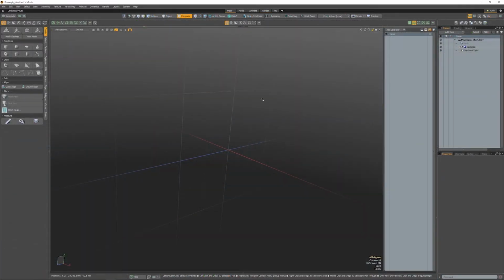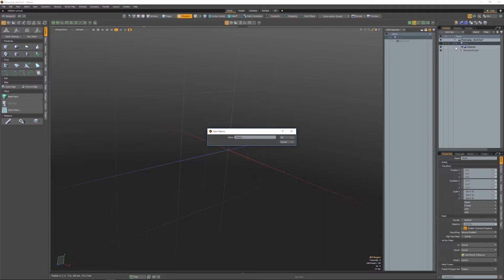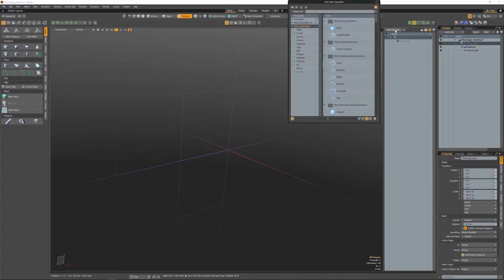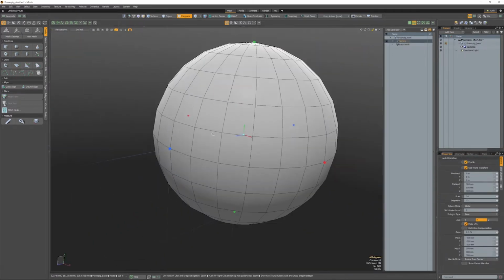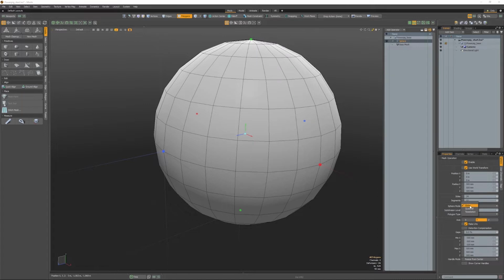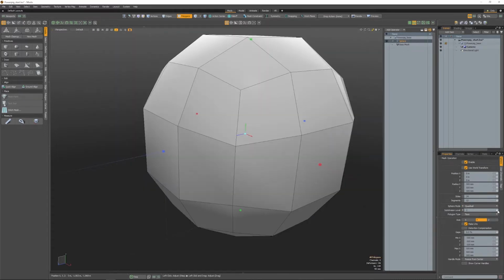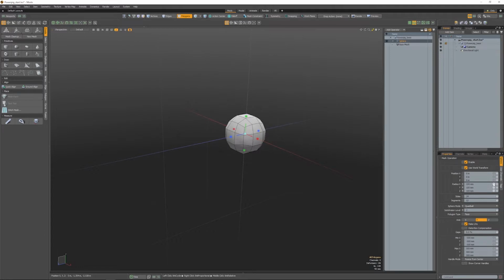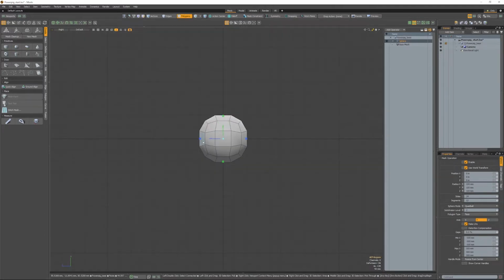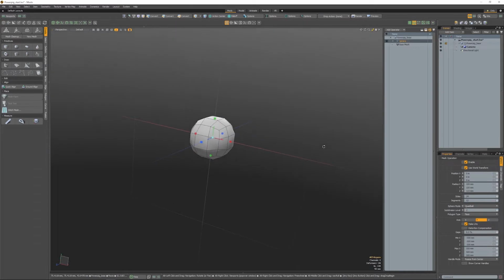Alright, so starting from an empty scene, you have here your mesh that I'll just rename, I'll call it power pig underscore base. And I will use procedural modeling for this, at least for the base. It's faster and it's more flexible. So I'll just come here to add operator and add a sphere. It comes in with 1 meter. I don't want it that big, and I want it quads, with 2 here, and 100 millimeters all over, right? And now if I change to the right view, I'll want to make it a little bit bigger on the Z, but this is okay, so I'm happy with this shape.